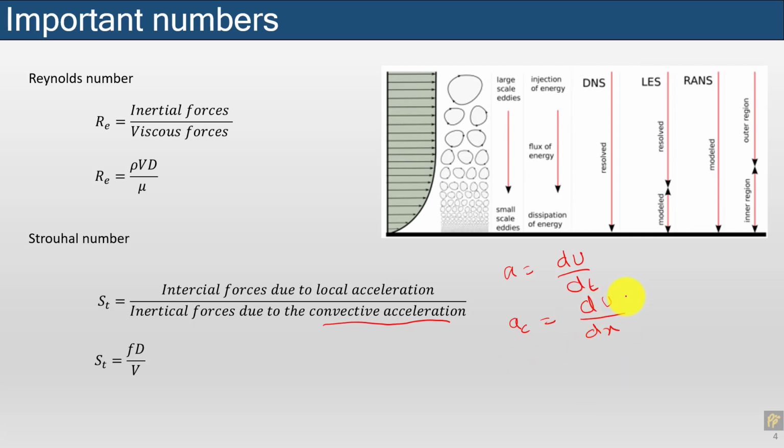The flow is still steady state, meaning it's not changing with time. If you take the example of a nozzle, we are not providing any energy to the flow, so it is accelerating because of the shape of that particular body. It is converting its pressure into velocity.